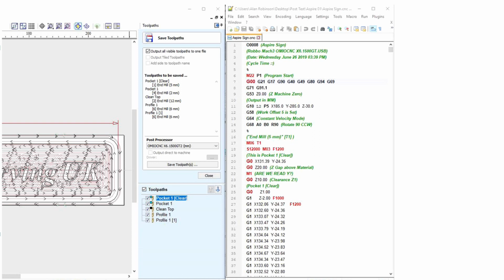In incremental distance mode, axis numbers X, Y, Z, A, B, C usually represent increments from the current values of the numbers. I and J numbers always represent increments, regardless of the distance mode setting. K numbers represent increments in all but one usage, the G87 boring cycle, where the meaning changes with distance mode.